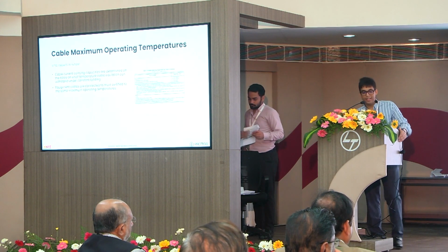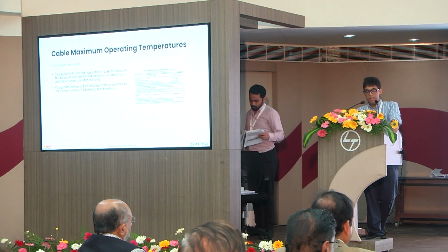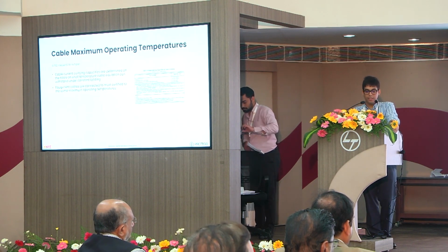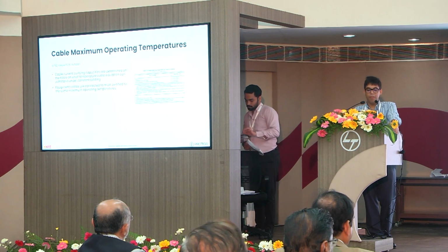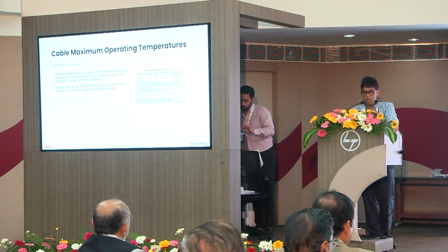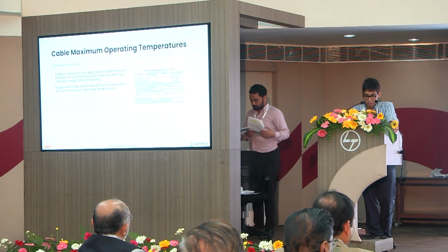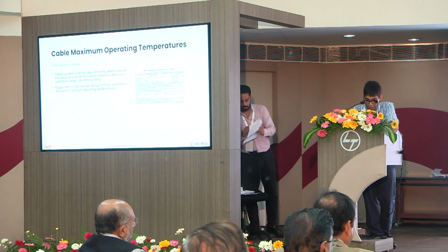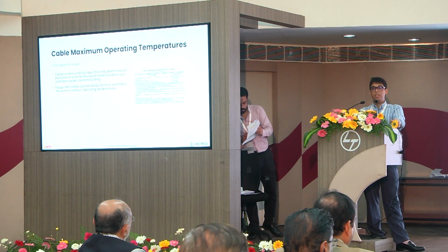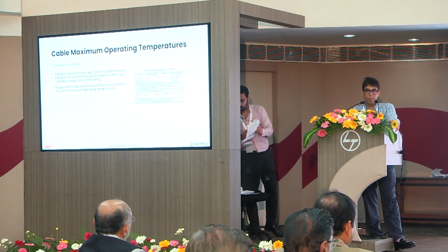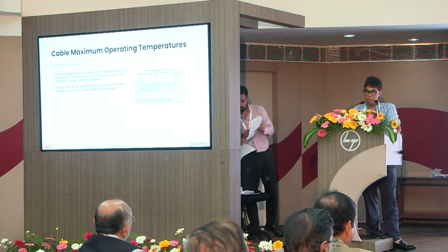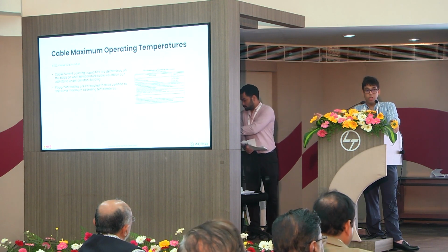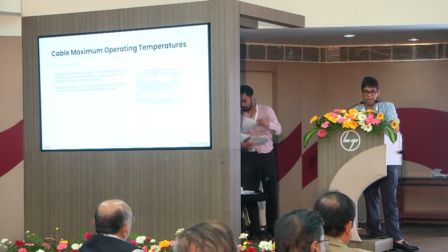Now this is an interesting thing about 90 and 70 degree conductors. If you look at Table 8 from IS 732, current carrying capacities are determined on the basis of what temperature the cable insulation can withstand under constant loading. We all know this. But if you look at the note, the second point, what it says is that if a 90 degree cable is being used and the terminals of the equipment you are connecting to are only rated to perform at 70 degrees or a lower temperature, or it is unknown, you cannot use the 90 degree rating of the current carrying capacity of the cable.